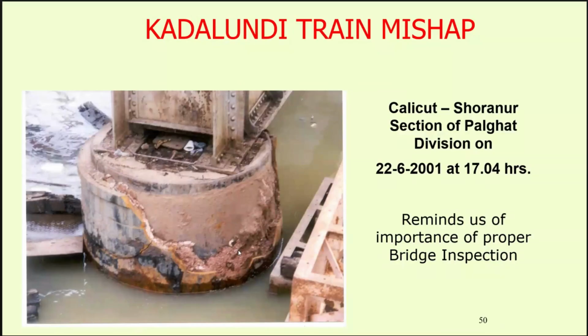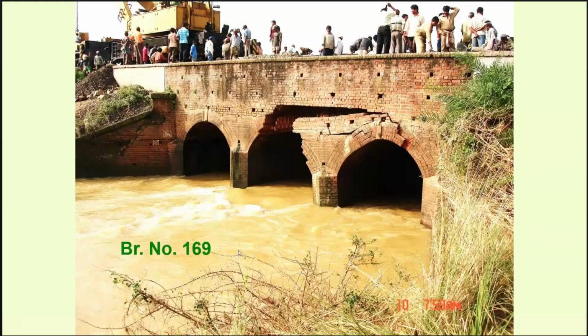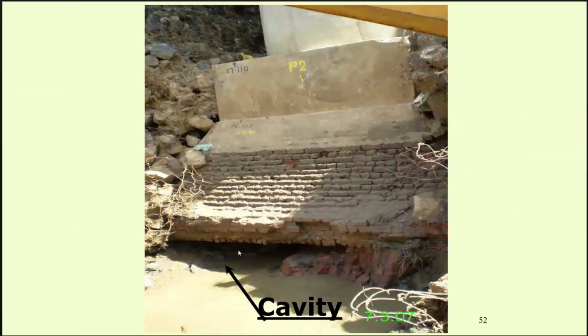In case of natural calamities like flood, if we take care in advance, then it is possible for us to mitigate and let our structure go through those natural calamities, and it will have a longer life. But for that we need to inspect in time and take precautionary measures or repair in time. So that is why we need to understand which structural components are getting affected. Because of this, open foundation is often susceptible to cavity formation below the founding level.